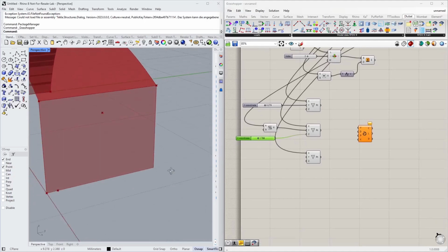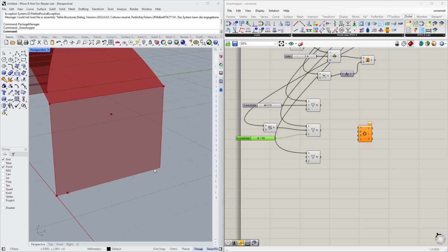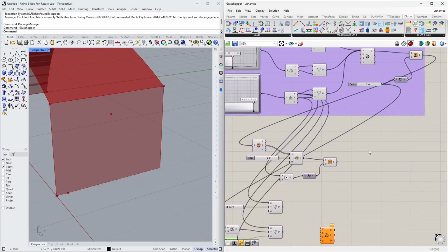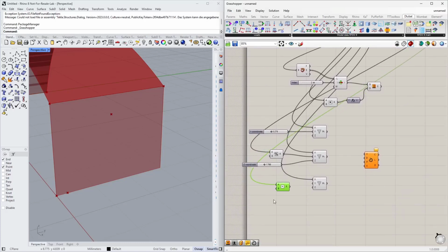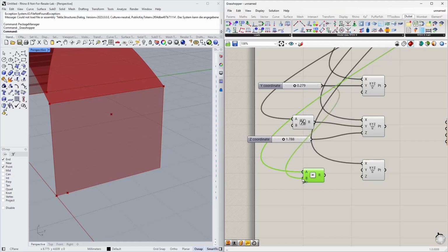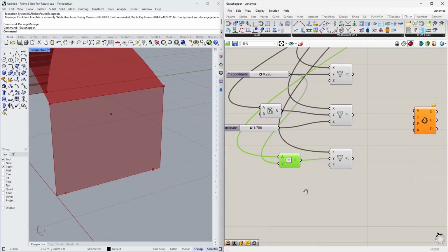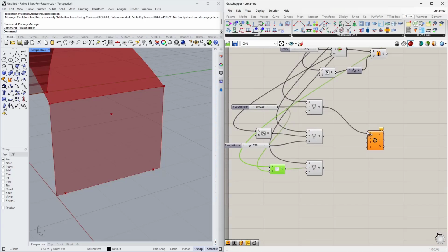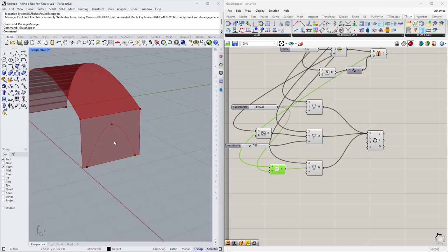And the last point is again on Z on the bottom of the surface, and it should have the same distance as the first point. So again, I just do a little subtraction. I subtract the extrusion length from my required support length. That's the Y coordinate. So whenever I change the length of the support, it will change on both sides. All right, these are my 3 definition nodes for my curve. And now we can see it.